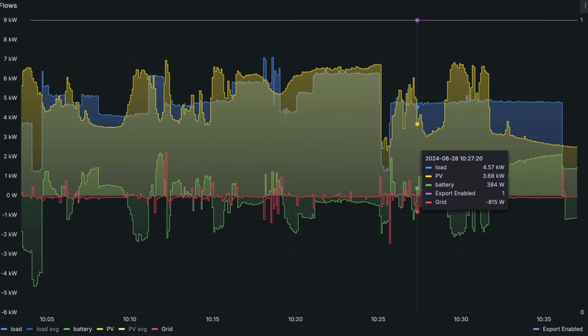And one more thing, when it's a cloudy day, the PV power output can change quite often, but I don't want to switch the wallbox off and on all the time. So whilst the automation adjusts the power every minute or so, when I switch on the wallbox, I start a timer that will prevent switching it off again for the next 15 minutes. So sometimes I can actually see that the solar output dipped below the minimum charge power, or that I could achieve more by turning on more phases. But then the house battery would cover the delta, or it gets an extra charge for a couple of minutes. And when the timer expires, it will adjust the number of phases, so that it would only be temporary.